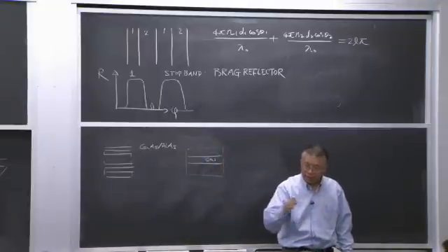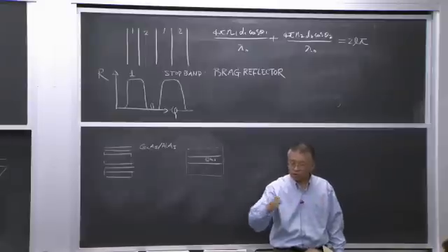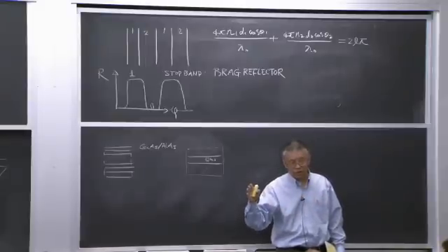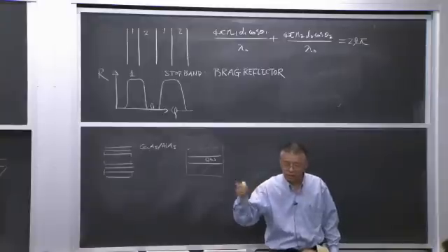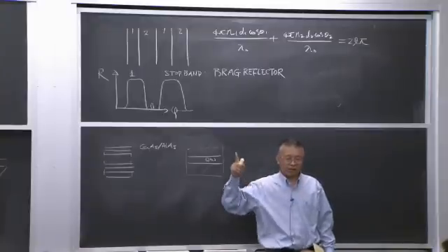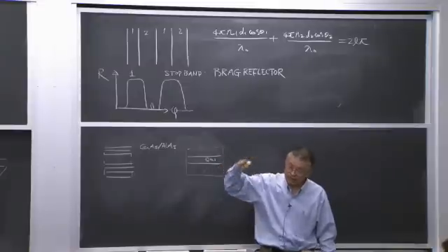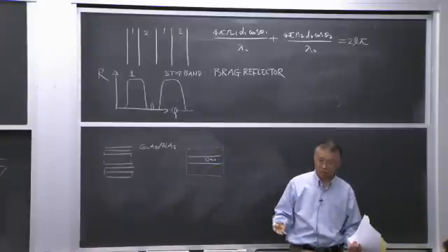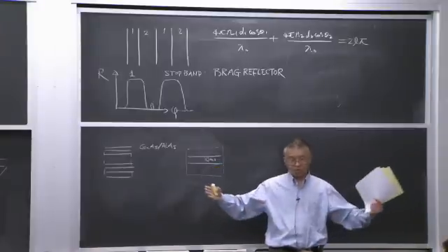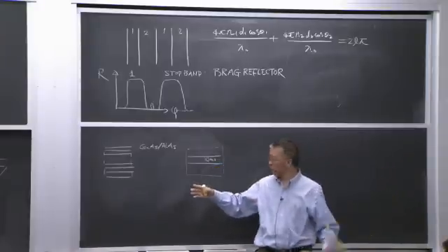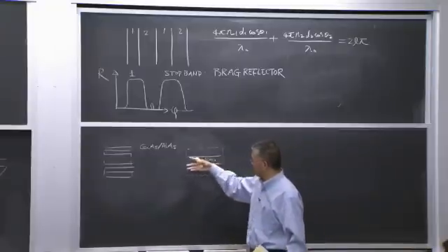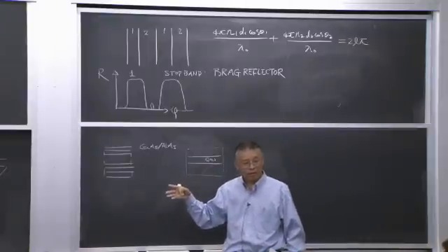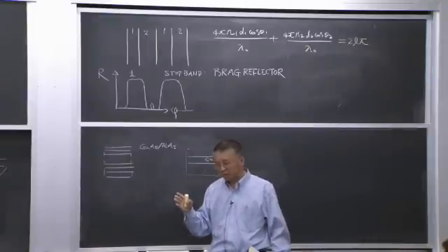And the light needs to be amplified, so it needs to go a certain distance, because the laser is amplified light emission, right? So the amplification is a negative absorption coefficient. We had before the absorption coefficient, where the light is decaying exponentially. And if you amplify, it's growing exponentially. But you need a certain distance to grow. So in this edge emitting laser, the distance for the light to oscillate is typically a few hundred microns.